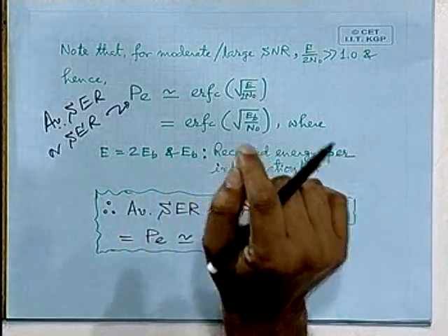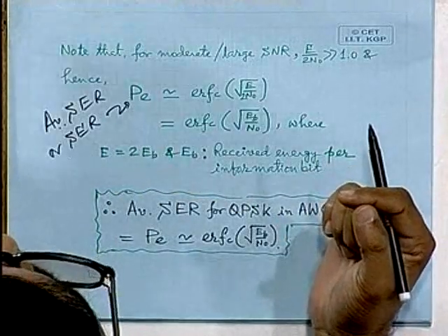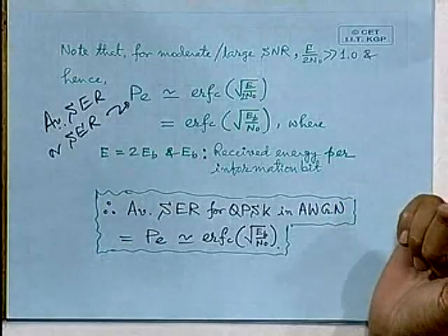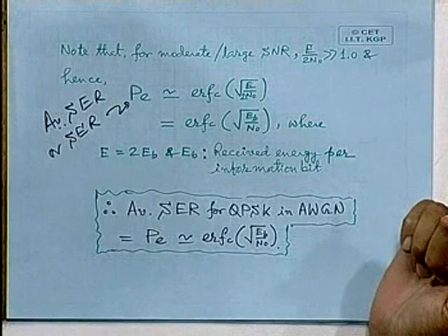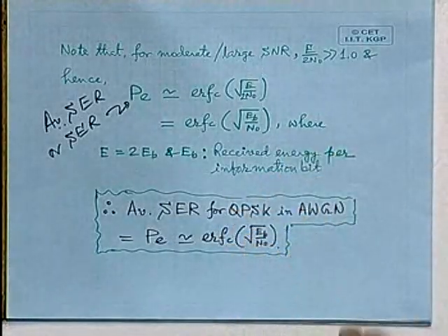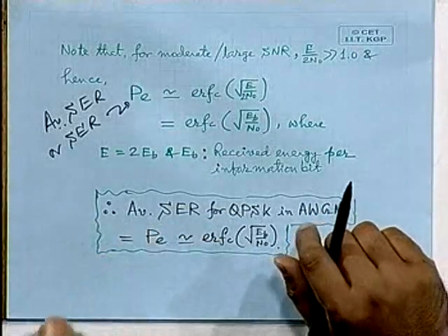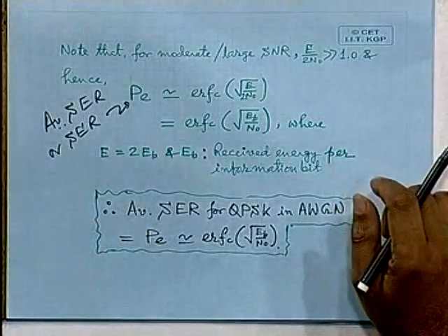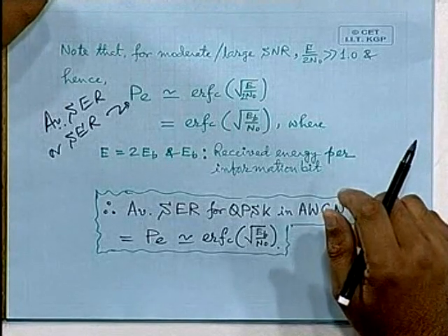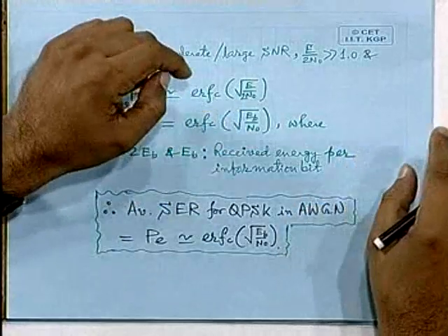Did you bother too much to see what is the minimum signal amplitude? You said, well, it was amplifying a 10 millivolt, 5 millivolt signal. But what happens if the signal amplitude is even smaller? If it is in the range of microvolts, the common transistor that you may have used will not give you an amplified output. You will find the output, with a lot of scale adjustment on the CRO, somewhat noisy. Very difficult to see, very difficult to synchronize the CRO, even if a sinusoid is being amplified.